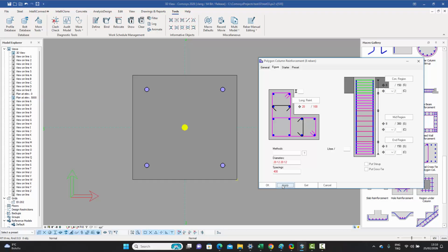Say OK. Now, if you notice, what happens is that the first side gets 2 because that's what 400 fits over there. The second side, which was the dark blue rebars, completely disappeared because they were eliminating their first and last rebars anyways. So there's no space for even one bar in the middle because that would reduce the spacing drastically. And the third side once again has these two, and then the fourth one disappears. So you will see occasionally the dark blue ones completely disappearing, and the reason for that is what you're seeing on the screen.